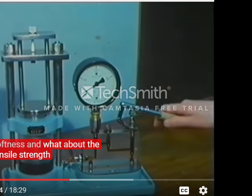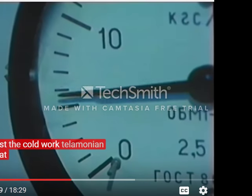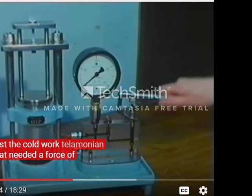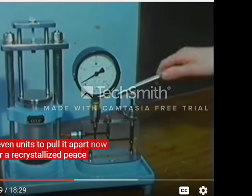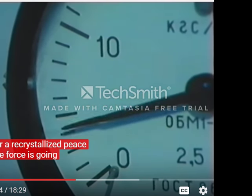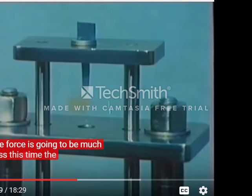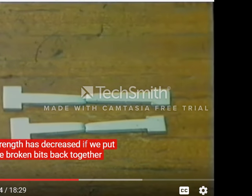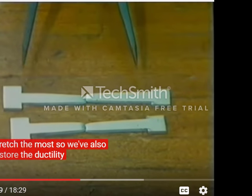And what about the tensile strength? First, the cold-worked aluminium. That needed a force of about 7 units to pull it apart. Now for a recrystallized piece. The force is going to be much less this time. The tensile strength has decreased. If we put the broken bits back together again, we find the recrystallized piece stretched the most, so we've also restored the ductility.